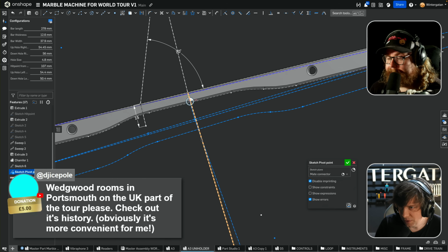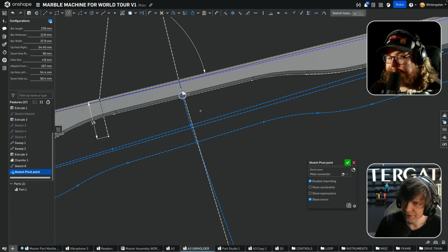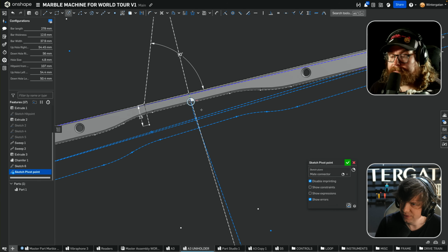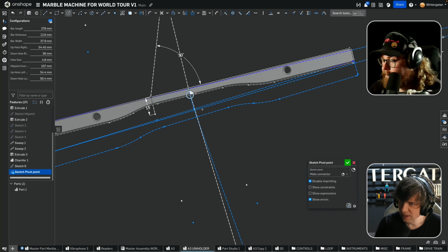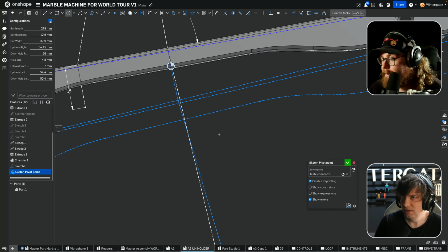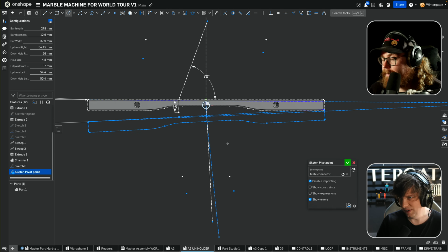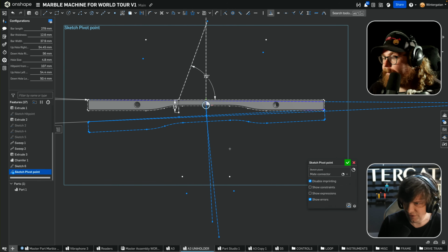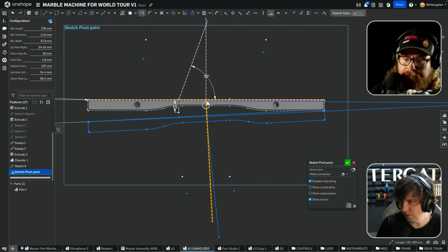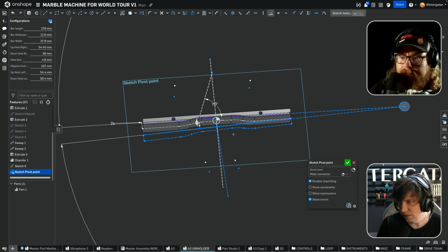So now, I'm going to draw the axle of the vibrating flaps. It should be on this white. Is this line really perpendicular? This is what I felt. This white line is wrong. Yeah, I constrained it wrong. Looks so wrong. So I think I need to go into this perpendicular constraint, remove it, and say Shift L. You are perpendicular to you. Okay, there we go. I thought it looked off.